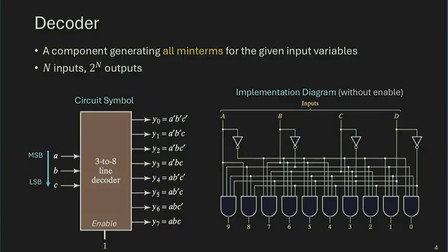It's called a one-hot. And implementation-wise, you can implement this as a bunch of product terms, right? Each output is a product function. So just you can put down 1 AND gate for each output. You have 8 outputs, you need 8 AND gates. You have over there 10 outputs for 4-bit inputs. You would put down 10 AND gates.